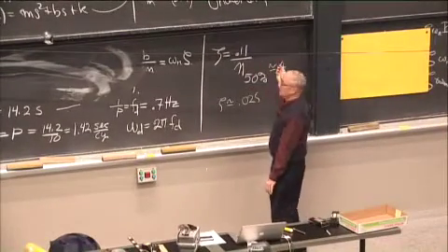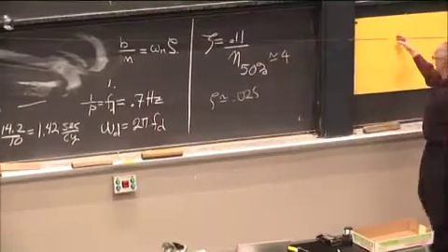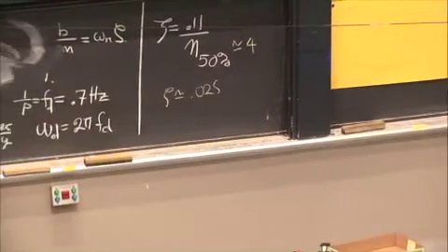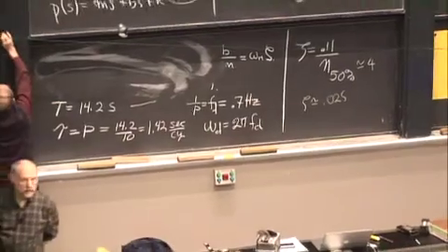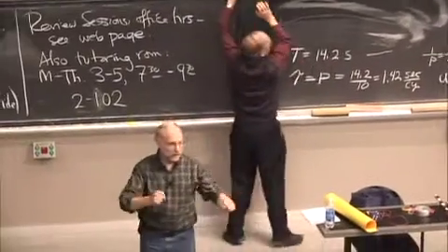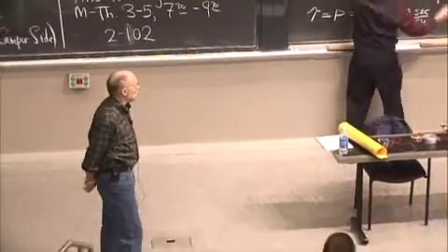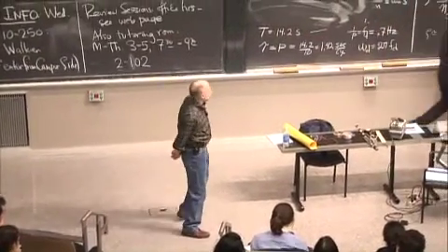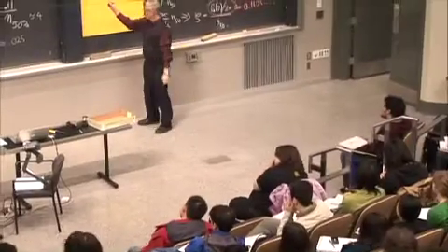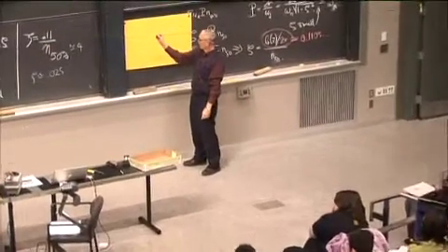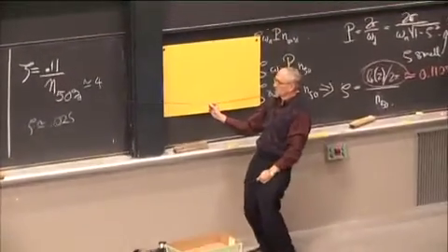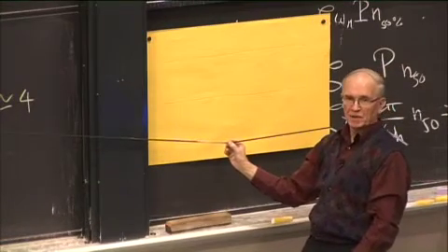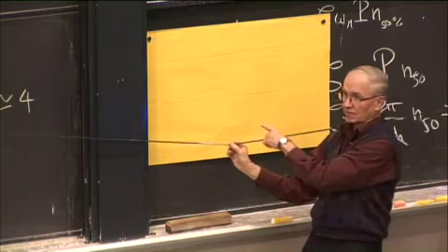So let's measure the damping of this string. We do the same thing, pull it down. I want to put my little stopper here so it lasts. So this string is a much more complicated system than the simple spring system we had. It's got infinitely many degrees of freedom. It's controlled by a PDE, but nevertheless, apparently its properties can be understood using the simple spring system we've just been talking about. So let's count roughly how many cycles it takes for this to decay 50%.